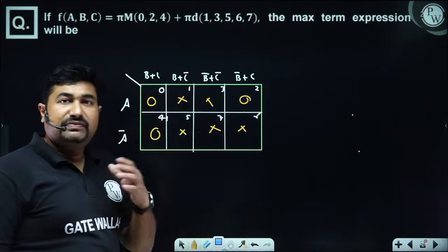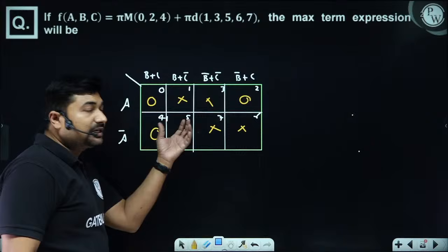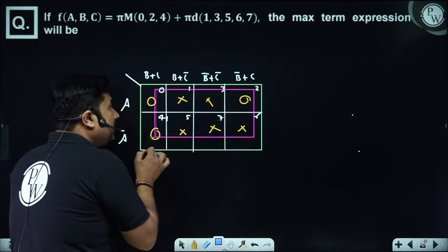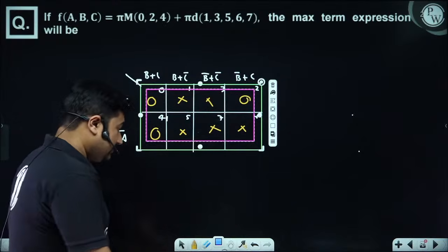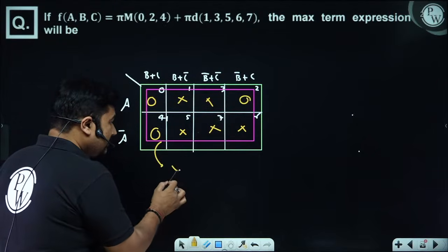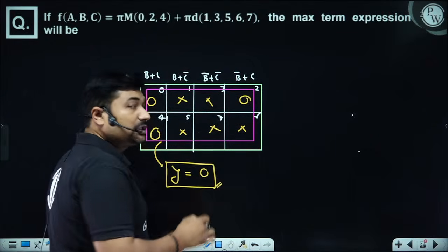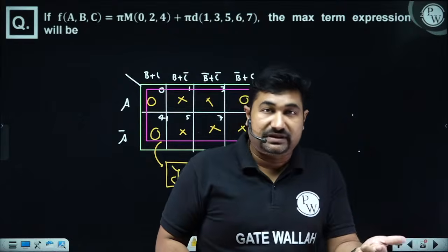Beta ji, the first preference is given to an octet. So if we select all the don't cares as logic level 0, we have an octet, which has the highest preference. And what is the minimized expression? Logic 0 and logic 1 is also a logical expression.